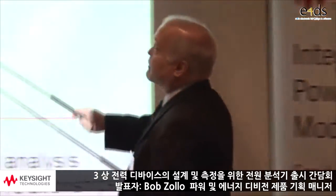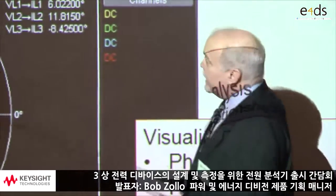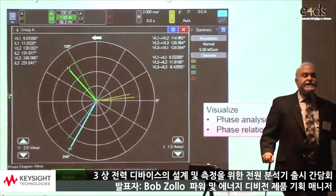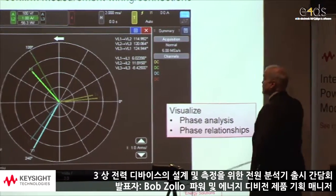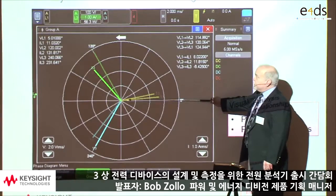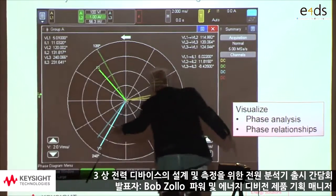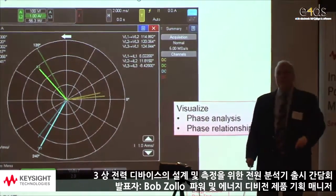So this diagram is called a phasor diagram. That's what they call it in the industry. It's a polar plot that shows the relationship between the 3 phases of the AC power, hence why we call it a phasor diagram. It shows phase relationships. So the 3 phases are typically what we say at 0 degrees, phase 1, then at 120 degrees, phase 2, and then at 240 degrees, phase 3. So each phase is 120 degrees apart.